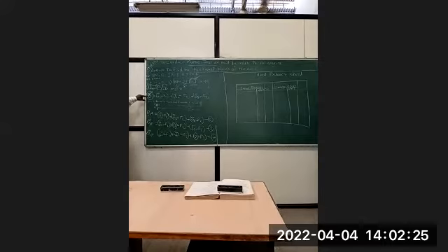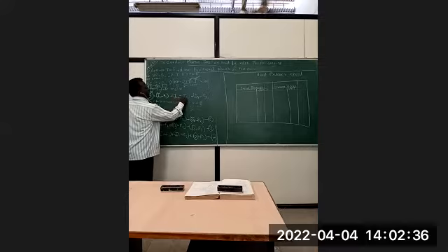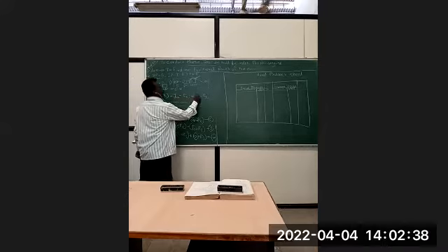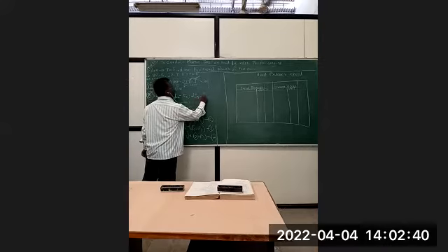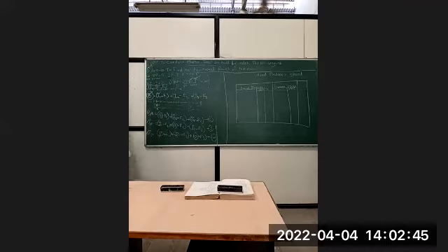So initially, we found the brake power when all the cylinders are fired. This was your brake power corresponding to when all the engines were fired. Then we had the power corresponding to when the first cylinder was not fired, so here we have written IP is equal to 0.